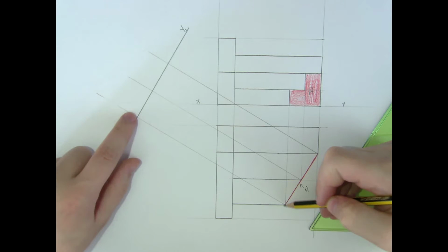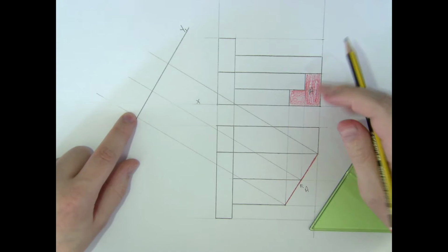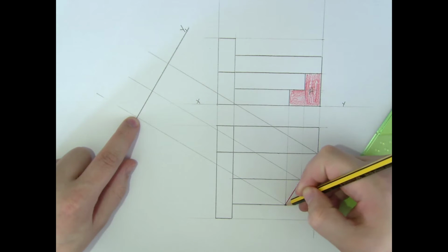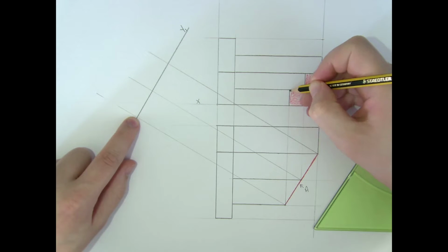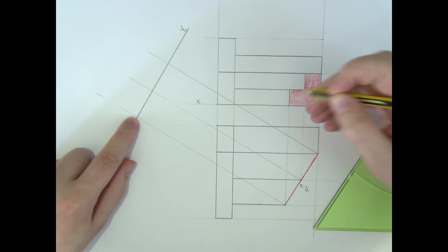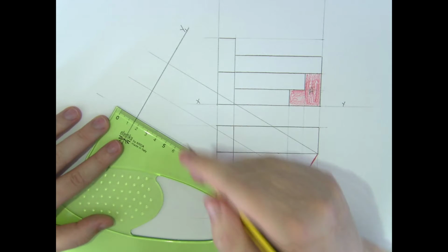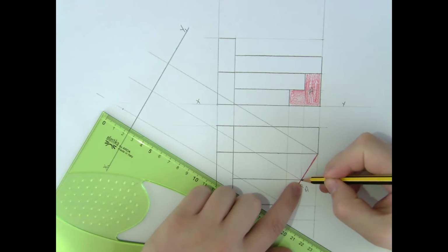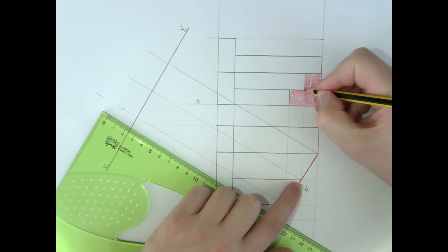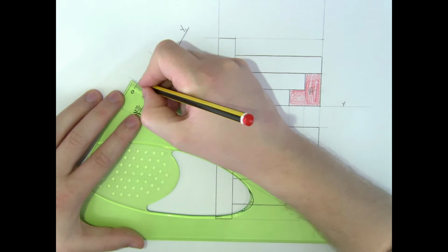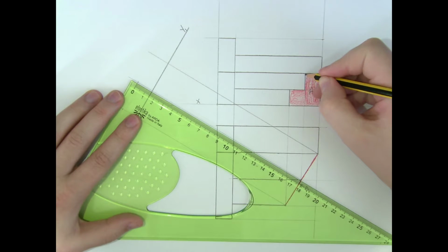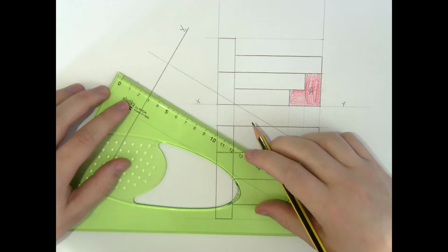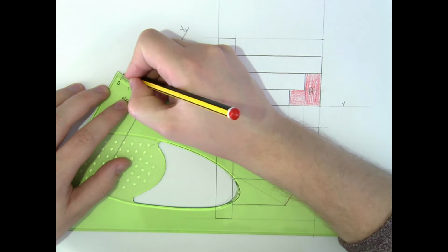So I'm working in this view. I'm going to move back through this view and take my measurement from this one. So from this point back to here, and I can take the height from this height here. This height is 15 millimeters, given in the question. For the next line, follow that back. That gives me this point. This height is also at 15, so the lower one. But the upper point of it is up at 30. So we can mark the upper height of this at the 30 mark up there.